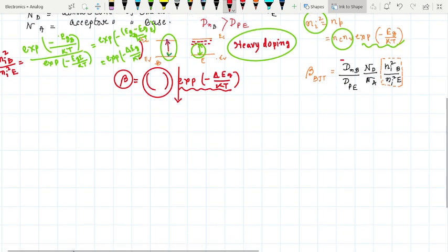Okay, now our main aim that we have mentioned earlier is HBT. So the first condition or criterion to make heterojunctions is that the lattice parameter should be very close between the two junctions. The lattice parameter of the material should be very close. The next thing is the linear expansion coefficient should be very close between the two elements. And the third one is the electron affinity should be more or less equal.